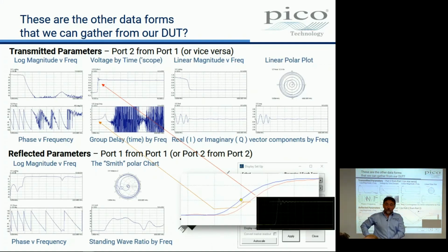If I use my mobile phone and I output data from the mobile phone, my voice in the sense of data, it goes as a modulated signal, yeah? And the modulated signal has a bandwidth. So some of the data is being encoded at these frequencies and some of it's being encoded at these frequencies in the bandwidth. If the bandwidth was that bandwidth there, some of my data would get delayed more than other parts of the data.